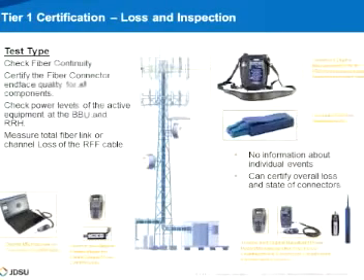That the correct fiber is plugged into the correct port. If you're doing insertion loss testing or OTDR testing, those lengths are the same, and it's going to be hard to verify that you are really on the fiber that you should be. So the visual fault locator, even though it's made to detect bends, is used as the verification tool that I'm on the right fiber and plugging in the right connector.